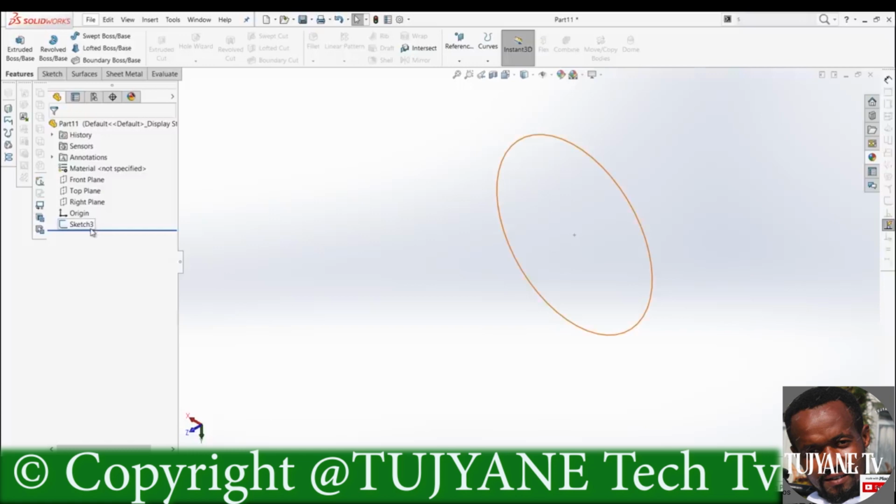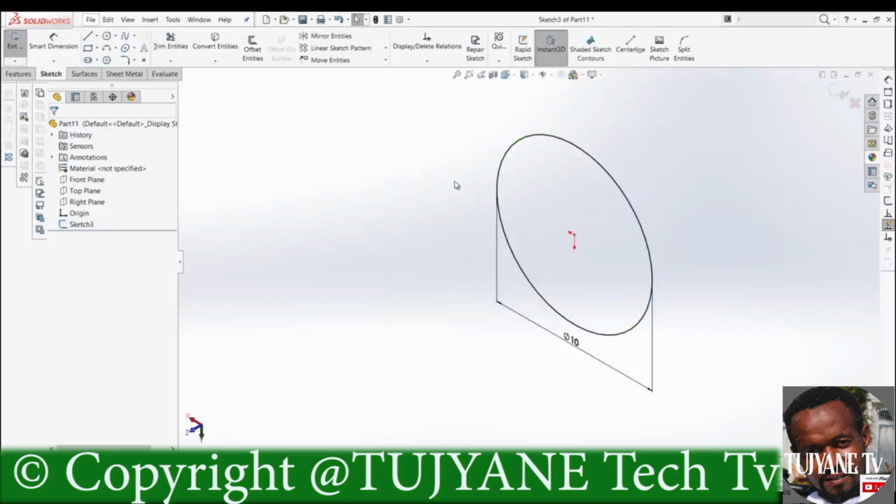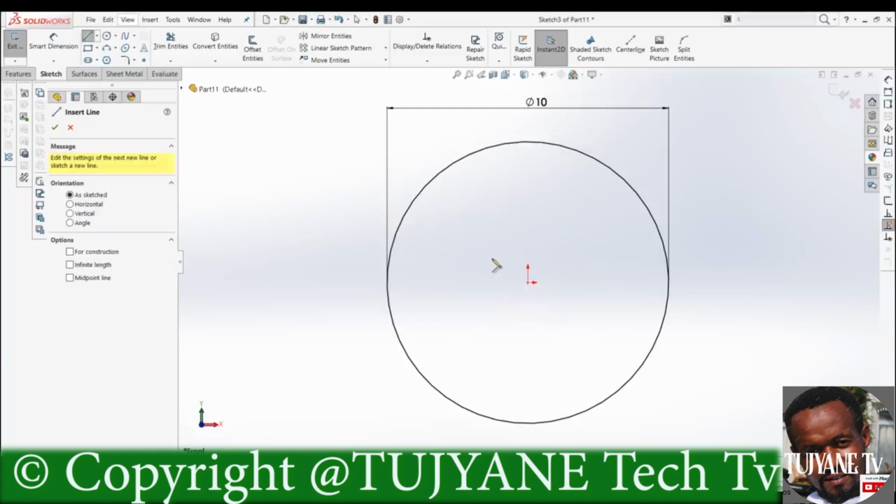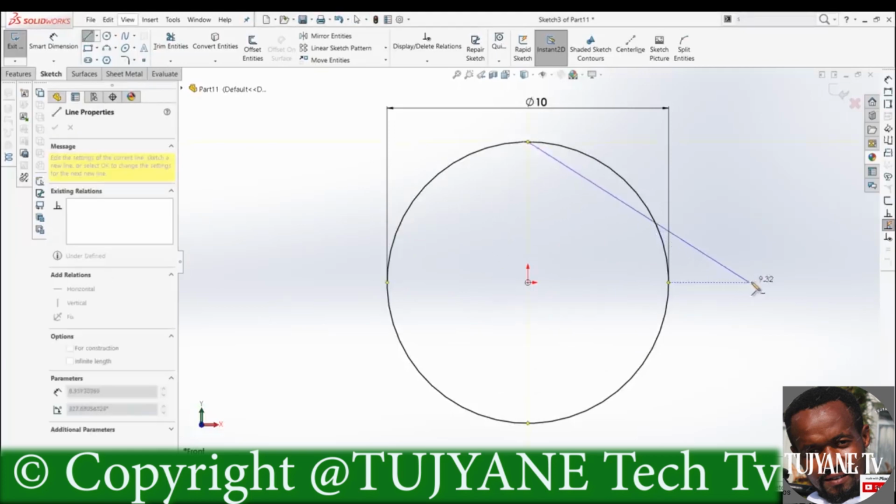If you haven't figured that out by now, an entity is basically anything you draw. Press Escape. Now my circle is divided in half and I have to get rid of one half. For that, I need Trim Entities. This tool offers 5 different types of tools to trim or cut your entities. I want you to forget these bottom 4 and only use the Power Trim for the first year of your practice. To use the Power Trim, you start off by clicking anywhere and hold your left mouse key and drag your cursor onto whatever you would like to trim.